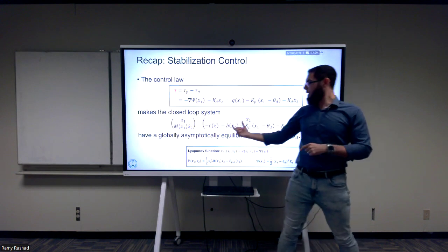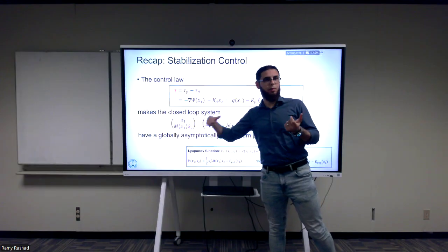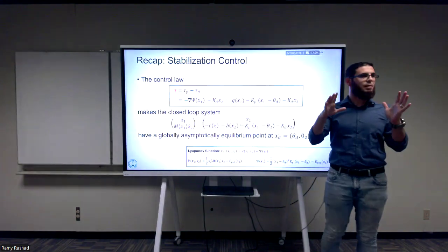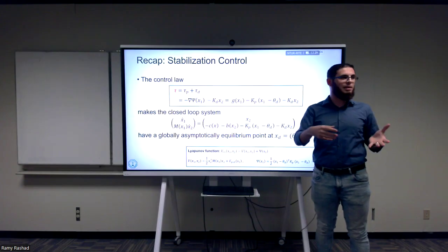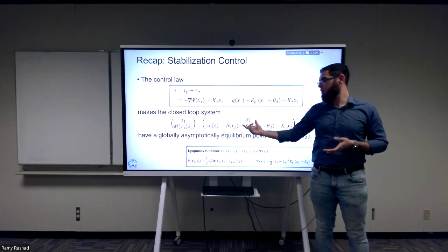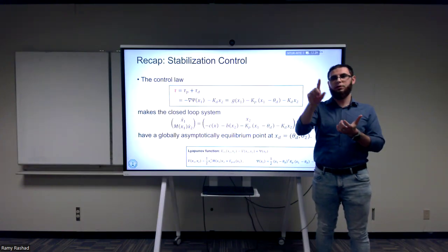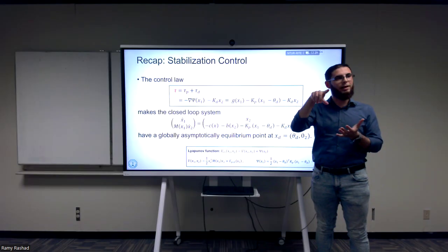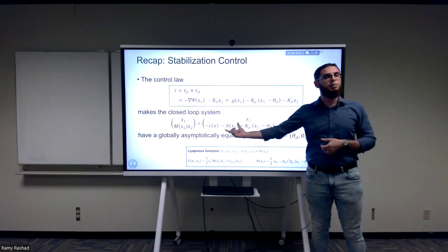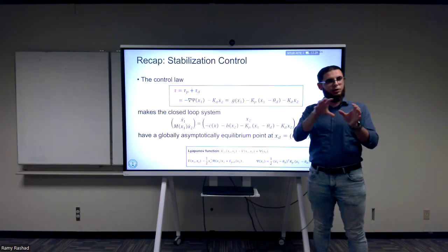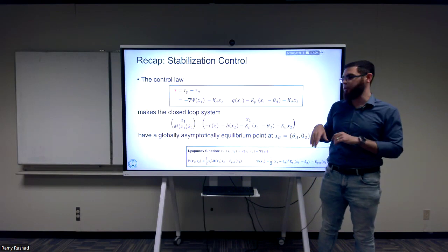Exactly. By looking at the relation between C and M dot, remember M dot minus 2C was actually a skew-symmetric matrix. This was exactly the same, for the same deep geometric reasons I never discussed. Remember when we looked at the rigid body rotation, the gyroscopic term that had the skew-symmetric form of the momentum? It also just disappeared from the equation, even though it was nonlinear. So whenever you see something that's skew-symmetric, always know there's some deep geometry behind it, okay, just as a side note.